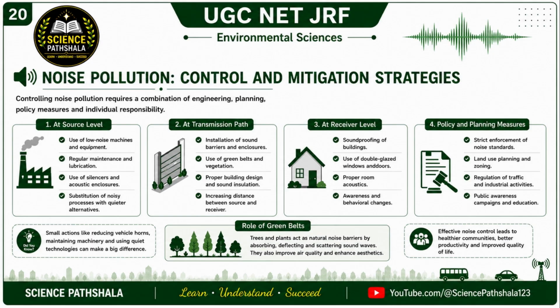First is control at source. Let's discuss the mitigation strategies in detail here. This is considered the most effective method because it reduces noise before it spreads into the environment. Source control methods include regular maintenance of machinery, lubrication of moving parts, use of silencers and mufflers, vibration isolation and adoption of low noise equipment. In industries, proper machine design and acoustic enclosures are also widely used.